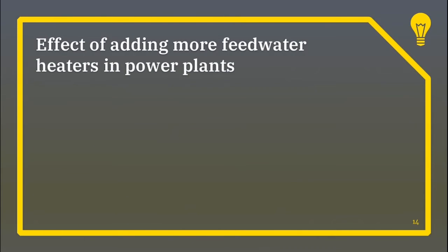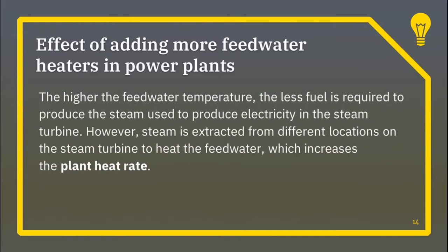What is the effect of adding more feedwater heaters in the power plants? Well, the higher the feedwater temperature, the less fuel is required to produce the steam used to produce electricity in the steam turbine. However, steam is extracted from different locations on the steam turbine to heat the feedwater, which increases the power plant heat rate.